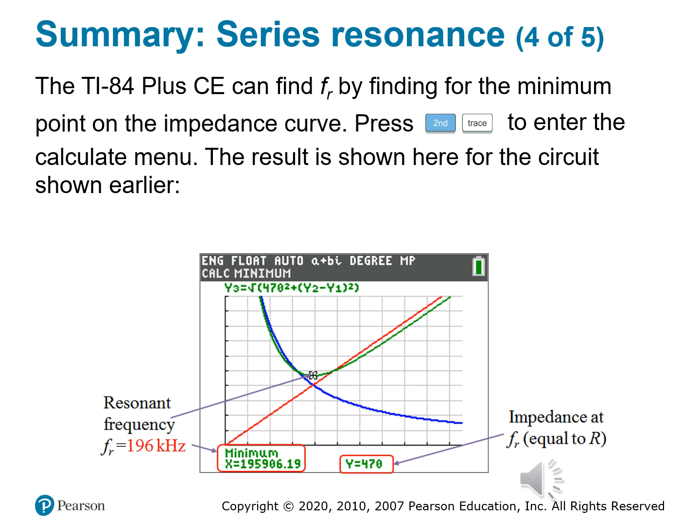And so what does it show you there on the graph if you're following along? It shows us the resonant frequency is equal to 196 kilohertz. So at this frequency, your circuit's impedance is at its lowest, and you're going to notice something pretty awesome. That impedance is equal to resistance. Z is equal to R. And what does this mean? It means that the reactive parts canceled out perfectly, and your RLC circuit behaves like a pure resistor.